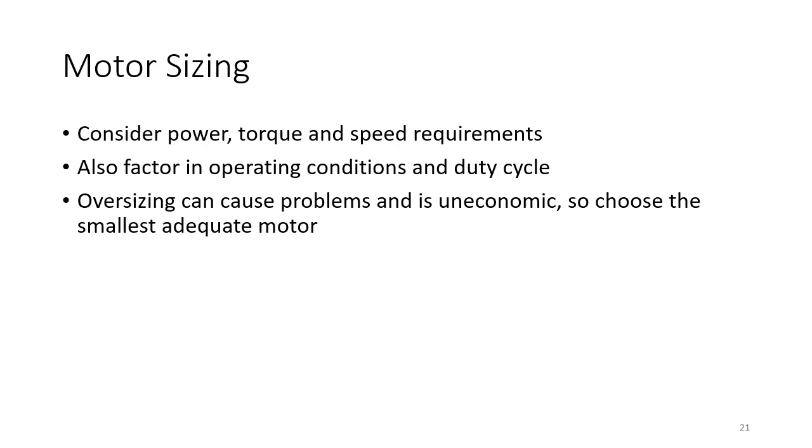Normally, what you would do is choose a motor that meets your requirements. Ideally, you'll choose the smallest motor that meets the operating conditions you have. You could use a larger motor, but first of all, it's uneconomic, and also having too large a motor can cause other problems. You might find that the motor is overcoming all of the other mechanics. For example, you might be driving a gearbox harder than it can go, which could cause problems with the actual mechanics. If you're trying to drive a conveyor too quickly, you could end up stretching the belt.